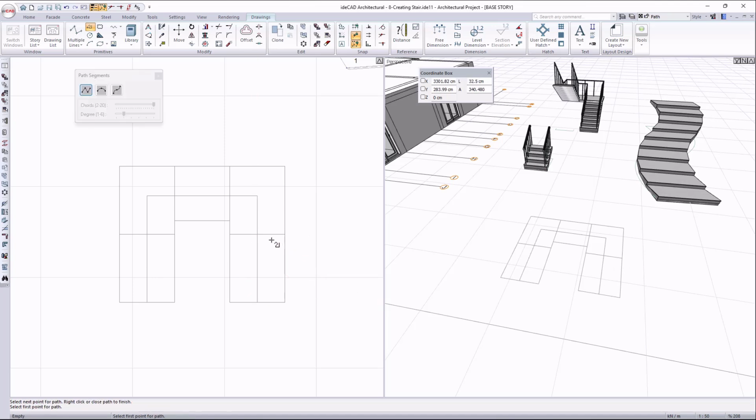While creating the second stair area, the landing, you'll notice that the second stair area is centered relative to the landing. One of the most critical aspects when creating new stairs is aligning the nodes precisely. For the stair areas to connect properly, it's essential that the nodes align correctly. Therefore, when drawing the second area, do not draw the shared edge in a single step. Instead, place nodes exactly where the nodes of the first area are located. After defining the boundary, continue by drawing the line of travel.